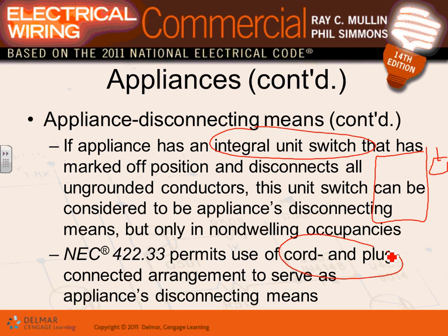Then they have a little cap to make sure that nobody is going to plug that big machine in while you're working on it. You first unplug it, and they have a cap. Put the cap at the top of that plug. Lock the plug, so now the plug cannot be plugged in. And that will be the locking mechanism. Lock and tag it for the plug. So that's for major equipment.